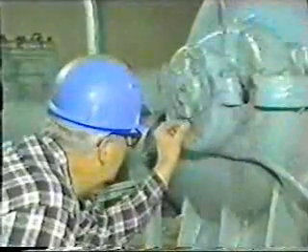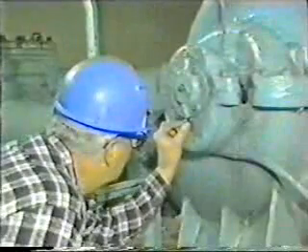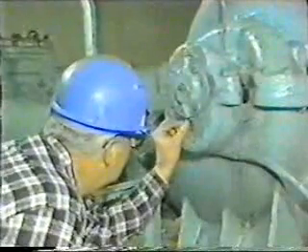It's important to verify as much as possible that your theory is correct. You don't want to make any changes unless you're sure your theory is correct. After obtaining facility approval, he'll check to see if the bearing has the right amount of lubricant and whether or not the lubricant is in good condition. It's difficult to tell if you have too little grease, but you can look for excessive grease.